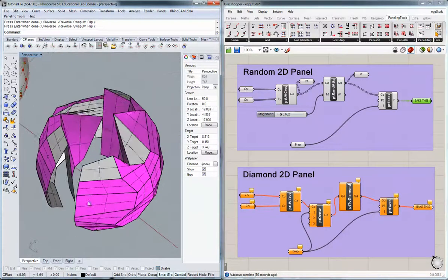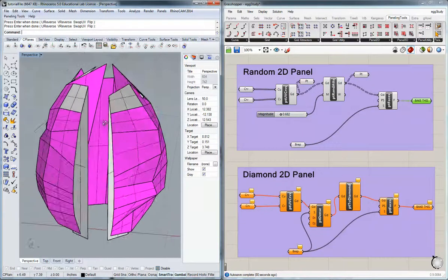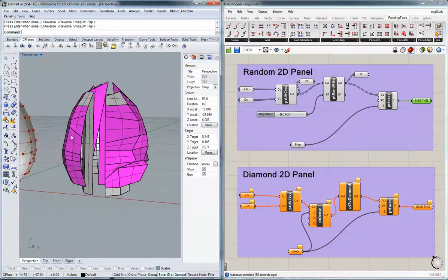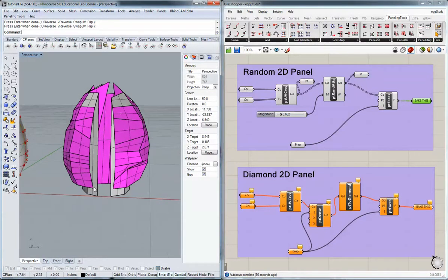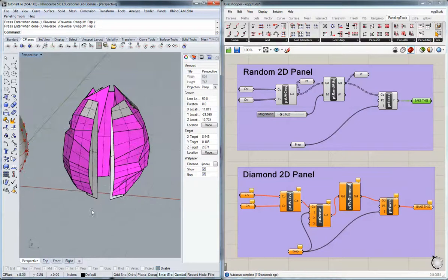And there's something really odd that was happening here. I'm not sure why that was, where, oh, I think this has to do with the selection order actually of those curves. I started at the bottom and I worked my way up, and then there was one more curve in the U direction at the bottom, and I clicked that last. So that actually dictated the order in which those points were generated. So you have to take care in what order you select the